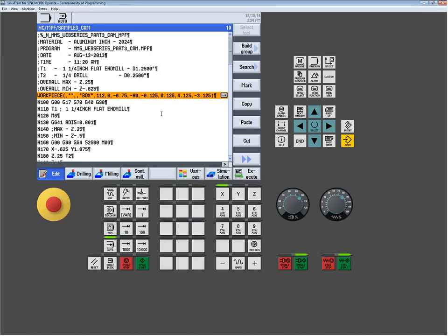I mean, all sorts of commands that are very critical when you get to 5-axis cutter path. And the problem is when you start to look at competitors' controls, they have all kinds of different variants of their own commands. So although the base program would read, if you had a direct axis program positioning A and C, it would work. But potentially you're going to run into probably a lot more pain. So we don't necessarily recommend running 5-axis programs in ISO mode.